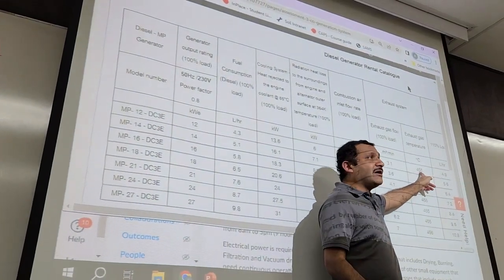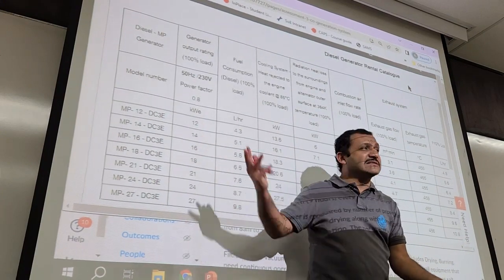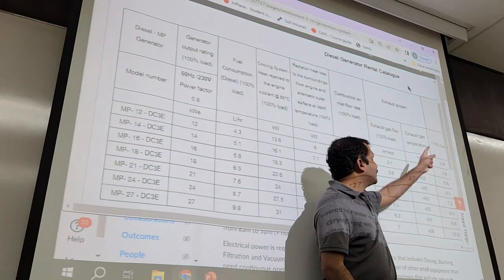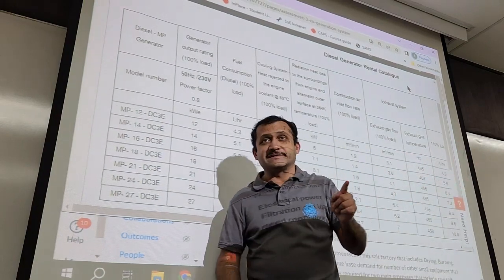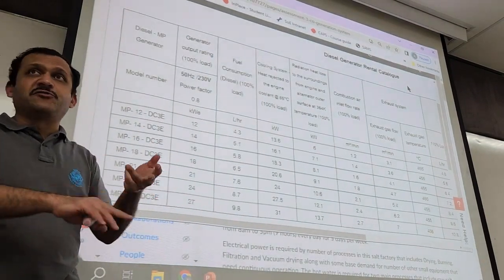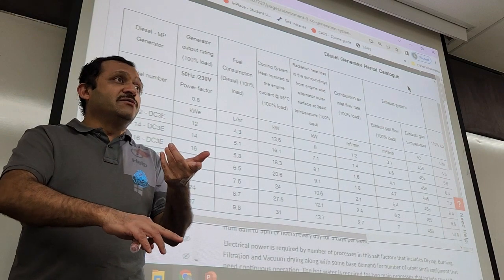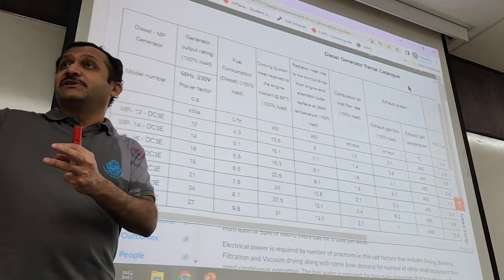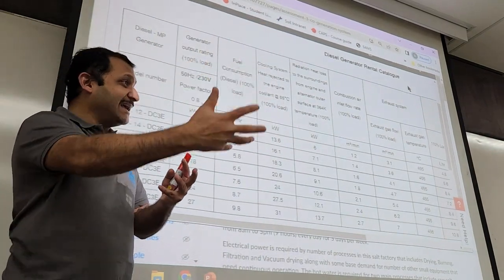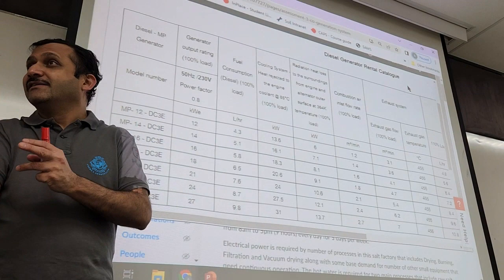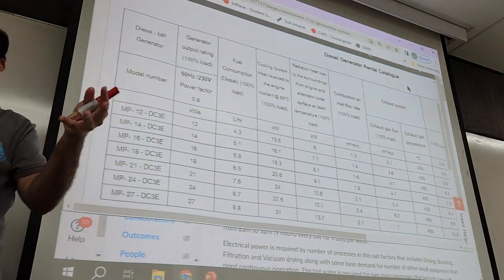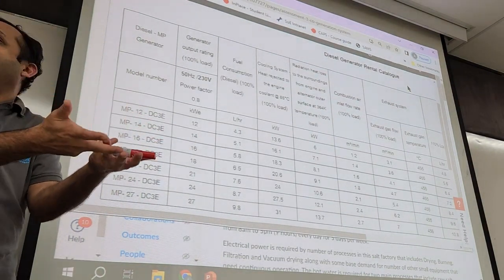There is a rule though. In theory, you can cool that down to ambient temperature, to 20 degrees Celsius. But as a rule of thumb, you should never cool down exhaust gas below 110 degrees Celsius. Why? Because exhaust from fossil fuels, diesel, petrol, natural gas, coal, which are hydrocarbons burning at very high temperature, the nitrogen from the air gets oxidized and you get nitrous oxide in the exhaust. Also water vapor, because there is hydrogen in the hydrocarbon, petrol, diesel, everything has got hydrogen and carbon.